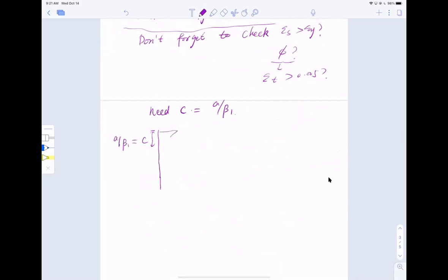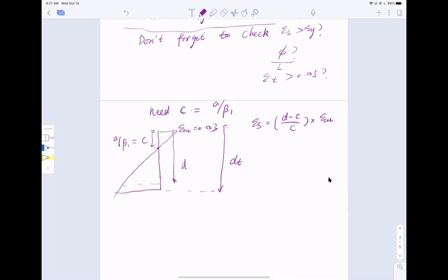And this is the compressive zone. So you know this is epsilon c equal to 0.003, and you have a depth right here. This is d, and you have all the way down here, this is dt. So how do you find epsilon s? It equals (d minus c) divided by c, multiplied by epsilon cu. Epsilon t equals (dt minus c) divided by c, multiplied by epsilon cu. Since we only have one row, the depth equals the last layer of the reinforcement.